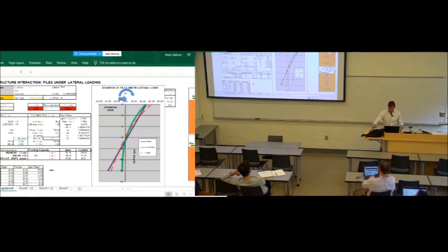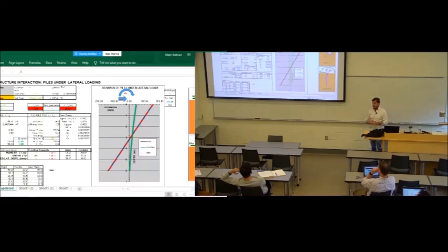And y prime 0, the angle at the top, is also given here. If we make a short pile, let's say 6 meters, look how the red line collapses now onto the blue line. So the equation I developed when I was your age collapsed and matched both theories. And we were very, very happy to discover this. And now I use it all the time.